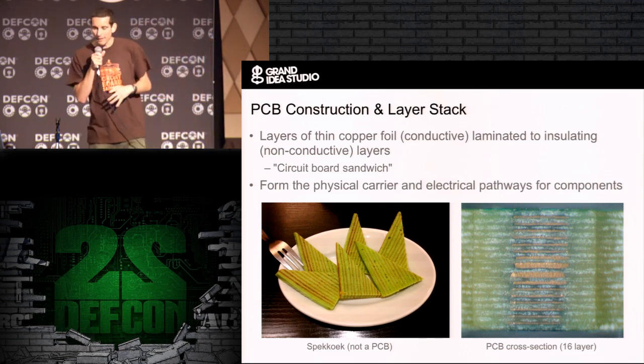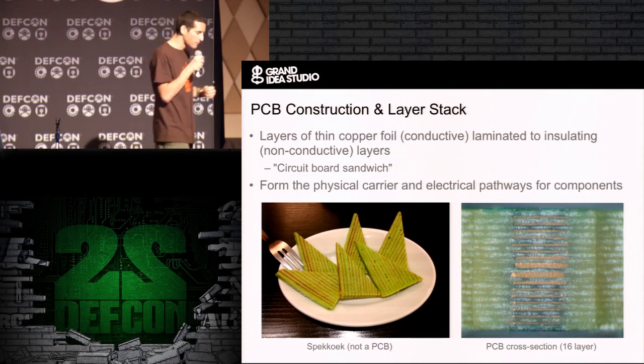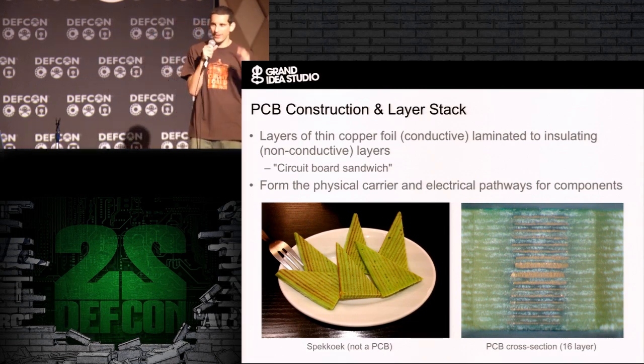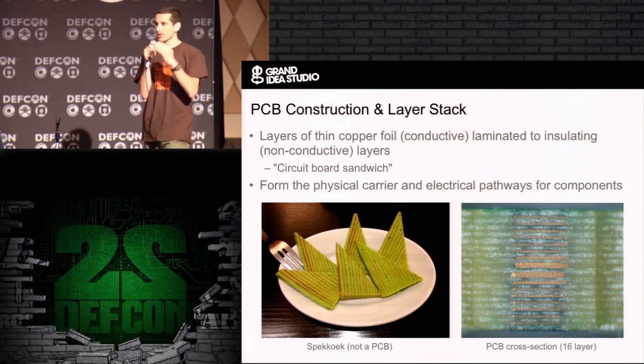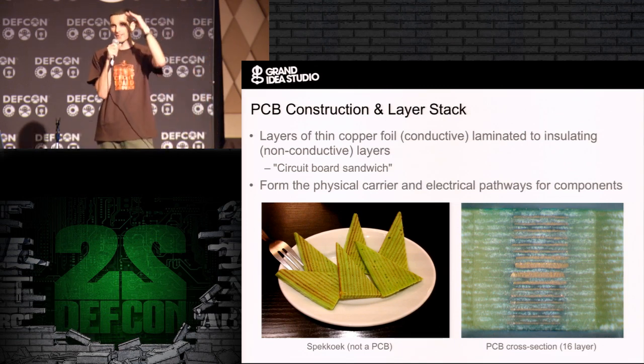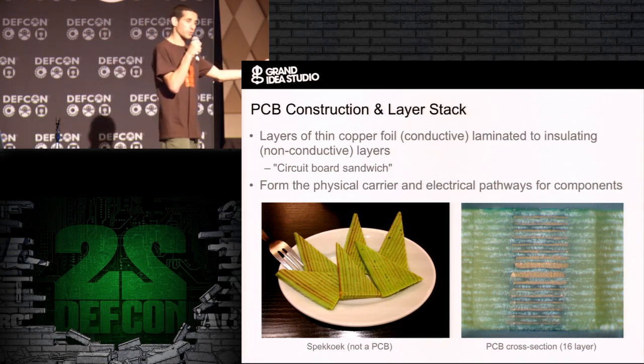That's pretty good. But circuit boards are basically a sandwich of layers. You have your insulating layers and your copper layers. Your top layer is going to be copper, then you have your insulating layer, and then another layer of copper and insulating. So I like to call it a circuit board sandwich.